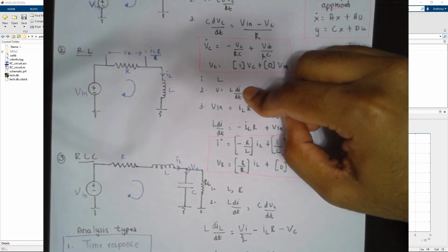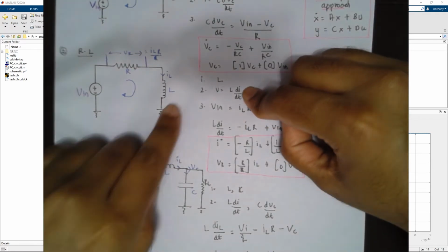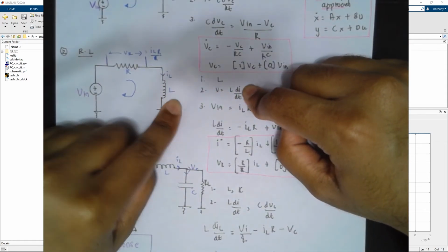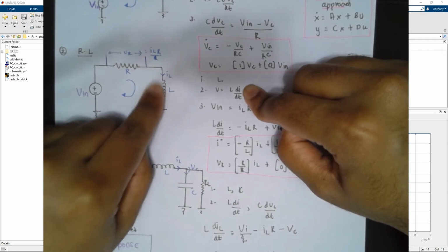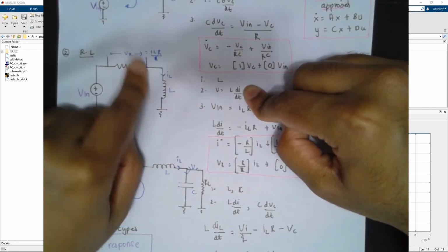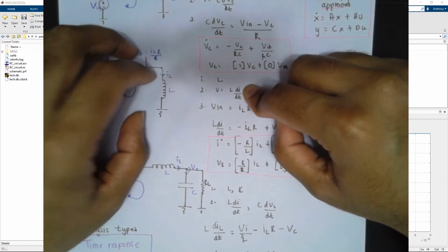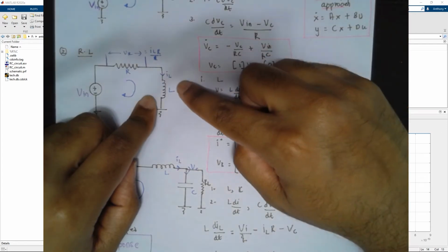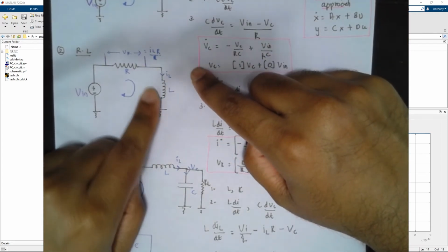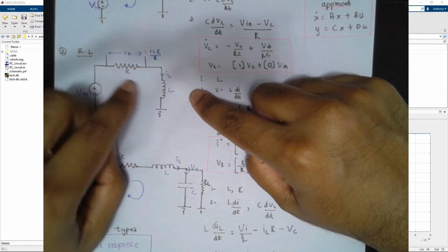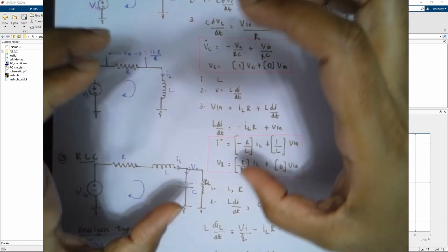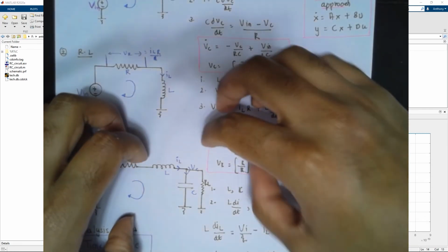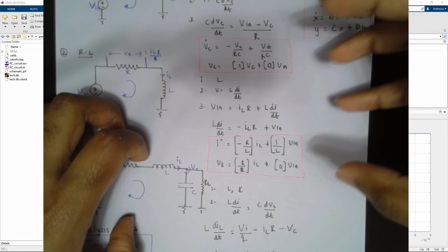Of course, a real inductor will not have these kinds of characteristics. A real inductor will have a little bit of capacitance and a resistance component to it. Almost all circuits will have this, and that's why the analysis is so important. When we are dealing with, say, an actual capacitor on a PCB, we have to model it as an RLC circuit because there's a little bit of inductance, capacitance and resistance in the practical capacitor, and we're using this lumped circuit model theory to understand the characteristics of that real capacitor.